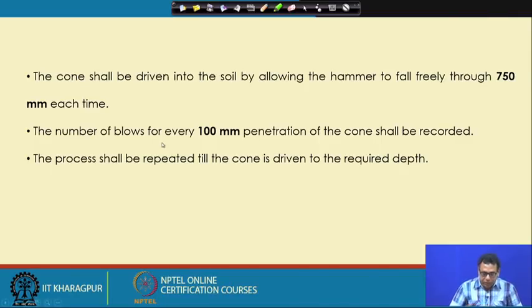The number of blows for every 100 millimeter penetration of the cone is recorded, and the process shall be repeated till the cone is driven to the required depth.